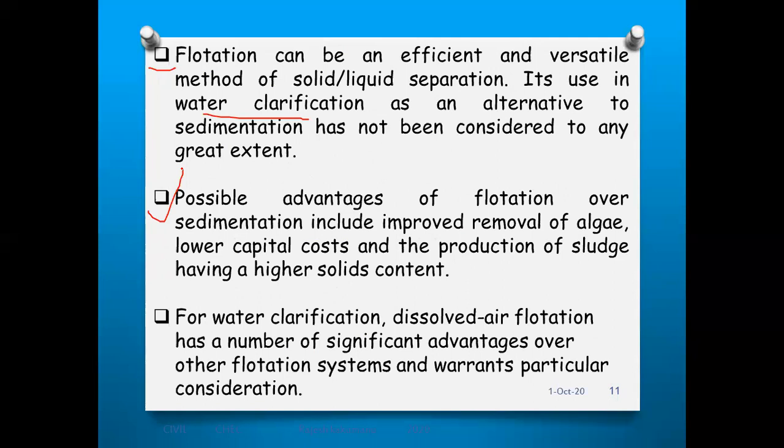Improved removal of algae, right? Improved removal of organic material, that is algae. And also, when compared to the sedimentation process, the flotation process is very small, therefore low capital cost, and the production of sludge having higher solid content.